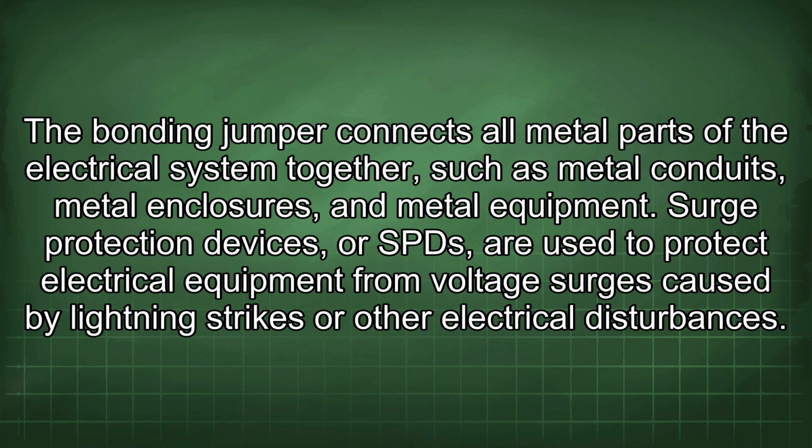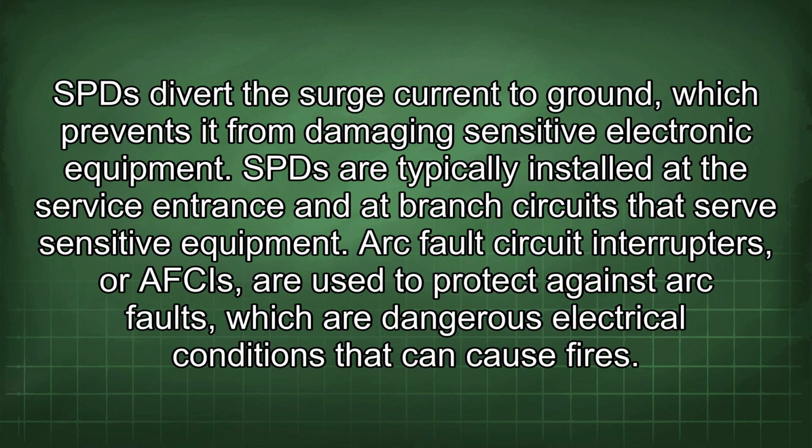Surge protection devices, or SPDs, are used to protect electrical equipment from voltage surges caused by lightning strikes or other electrical disturbances. SPDs divert the surge current to ground, which prevents it from damaging sensitive electronic equipment. SPDs are typically installed at the service entrance and the branch circuits that serve sensitive equipment.